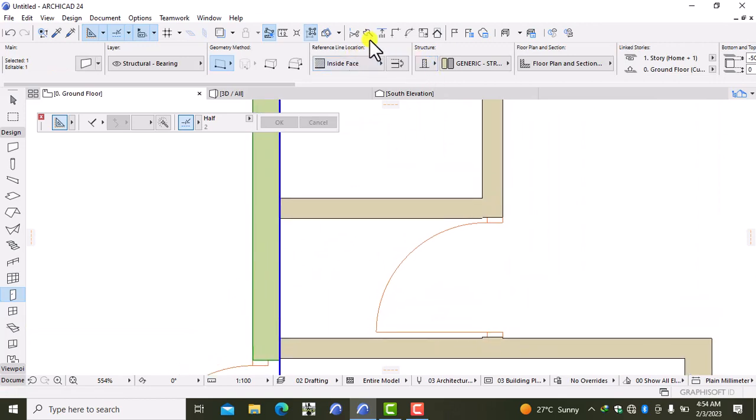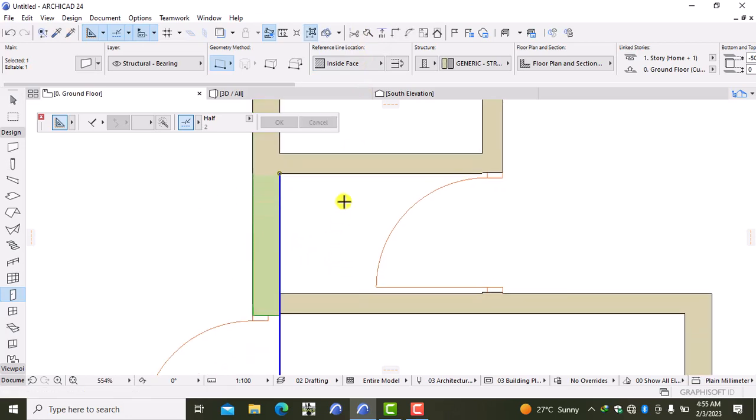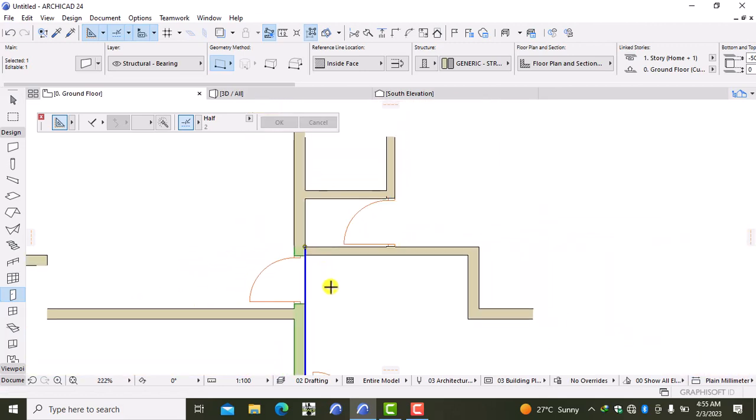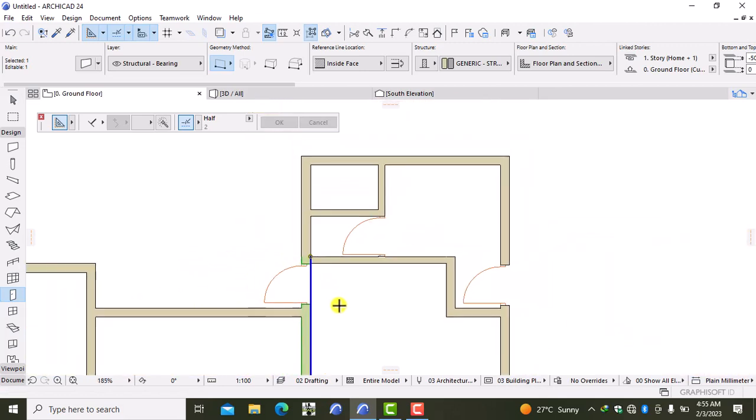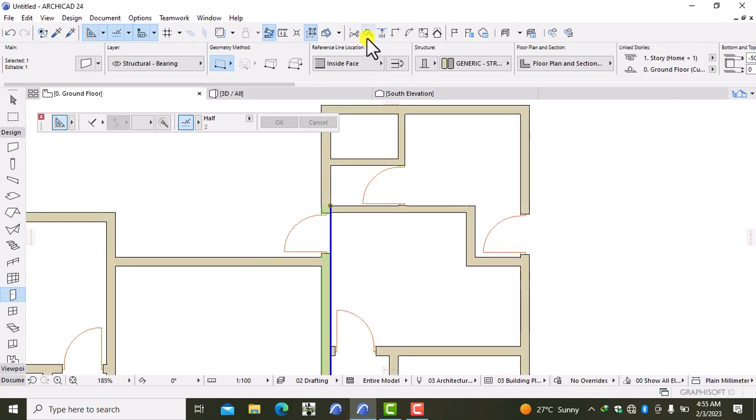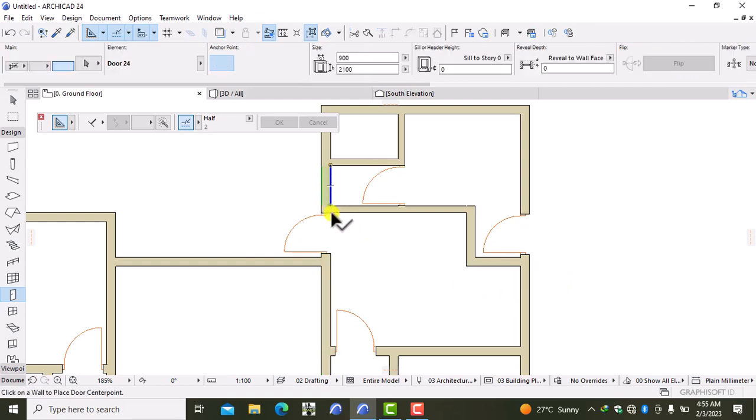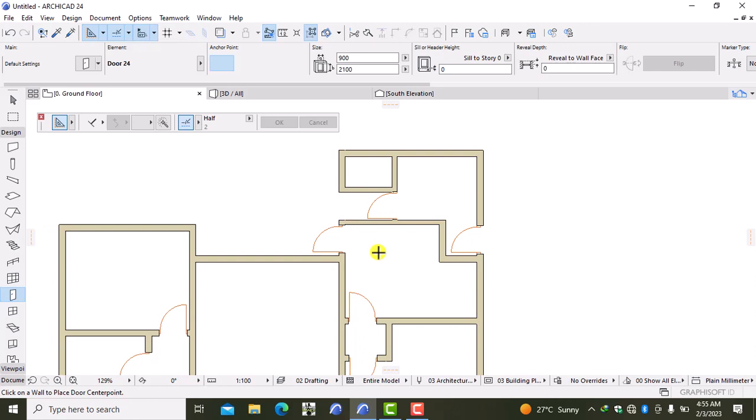I'm going to split this into two. This particular wall over here, so that I can be able to get rid of it. Still using the split tool. Recall what we did say on my previous video. In order to use the split tool, you just basically select, you hold Shift, you select your wall, and then you use this split tool over here to split your wall into individual elements. So that's what you have. Then you can get rid of this, so that it gives you access to your DSQ over there.